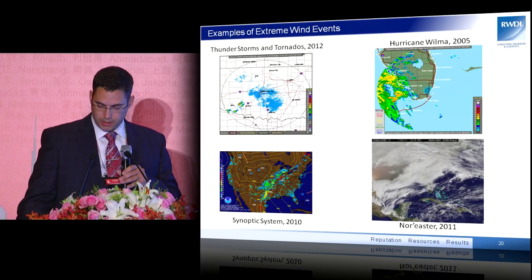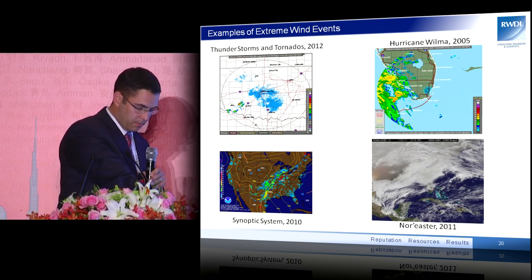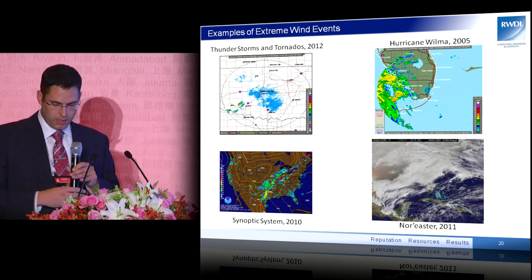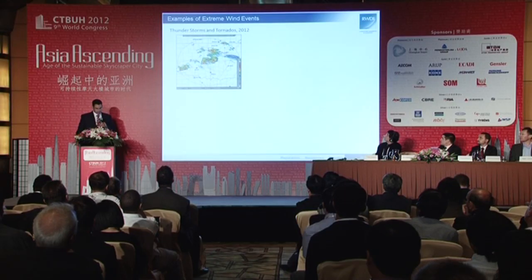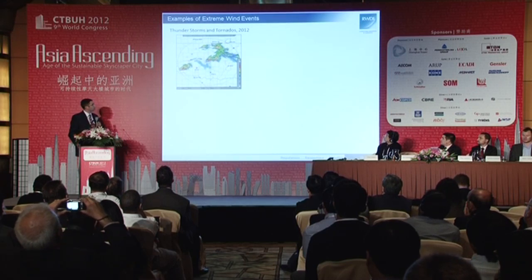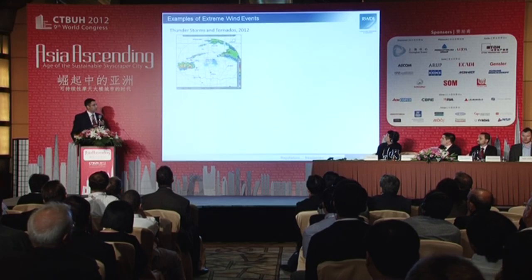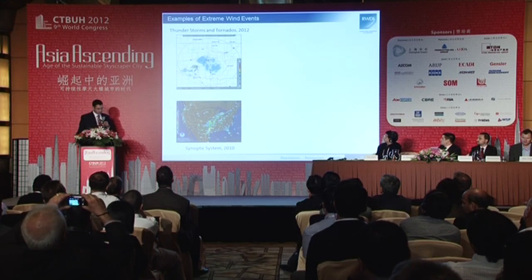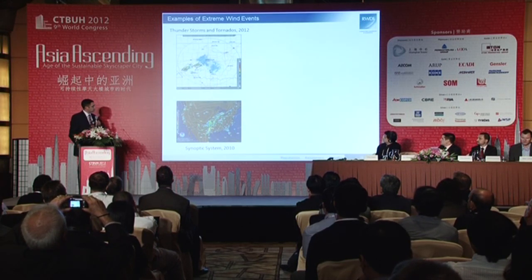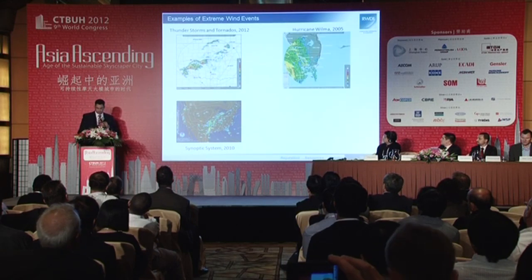So moving on to wind climate and some of the things that we're thinking about at RWDI, when we do wind tunnel tests, there's a certain model of the atmosphere that I'll mention in some detail, but just looking at some of the different actual storms that we need to consider, in a large part of the world, our extreme winds, at least close to ground, are controlled by thunderstorms. We have larger scale systems, some low pressure ridges or cyclones, sort of winter cyclones.